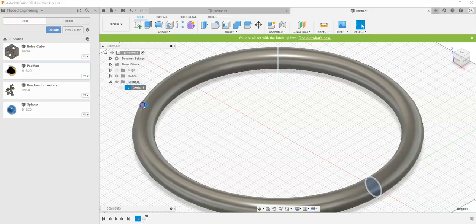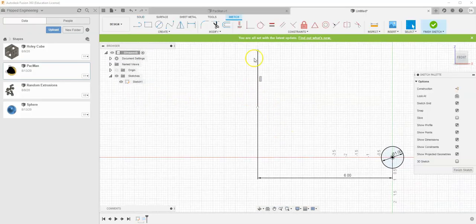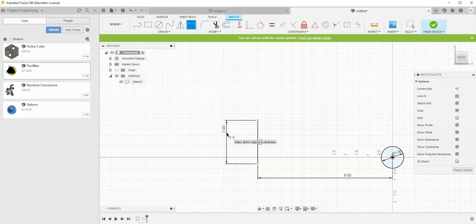And so let's go back into our sketch. These other dimensions don't actually matter. They don't contribute to our revolution in any way. This vertical location dimension or the length of our line. Those two dimensions don't actually matter when it comes to a revolution. But still, we're going to go ahead and add those dimensions because it's proper practice to fully constrain your sketch. So let's go ahead and hit dimension, and let's select our line, and let's tell it to be 2 inches in length.